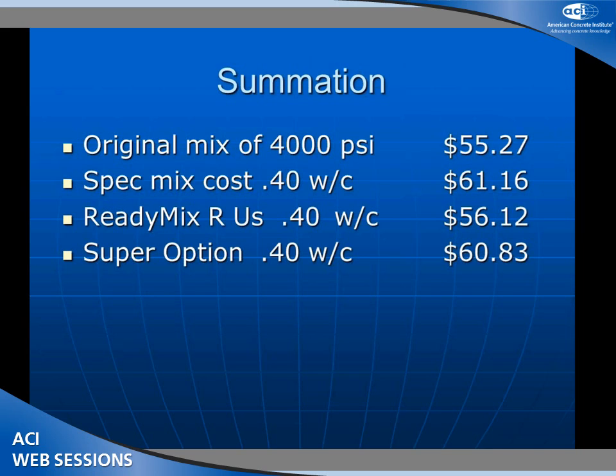The long and short of that whole story is the engineer called me up and wanted to know why my mix had so much cement in it. We were having problems in the field. Concrete was cracking and getting a terrible finish. We poured concrete in the middle of summertime at 637 pounds a yard. And I explained to him that that's the amount of cement it took to get the concrete out of the truck. And I said, you have a piece of paper and pencil? Let's start doing some math.